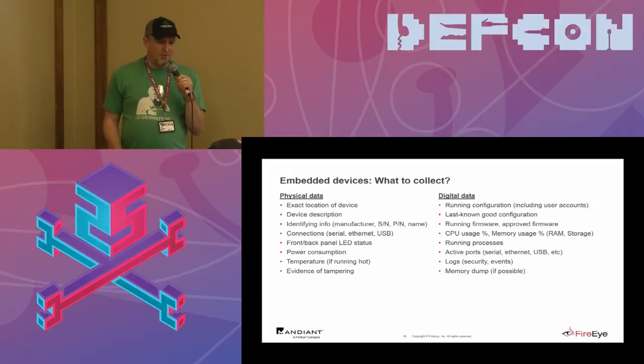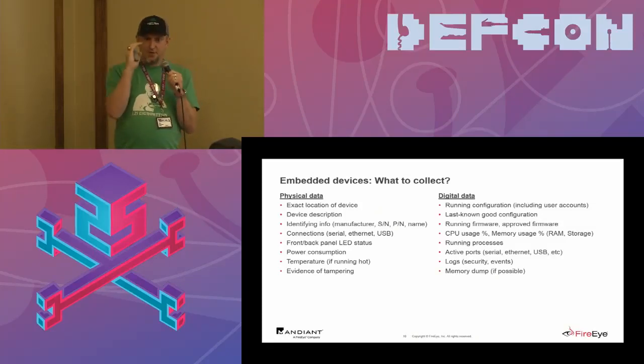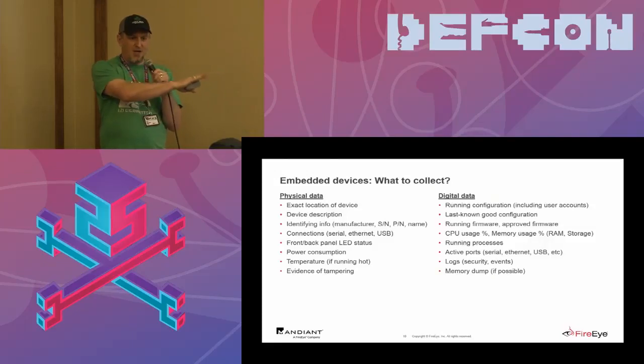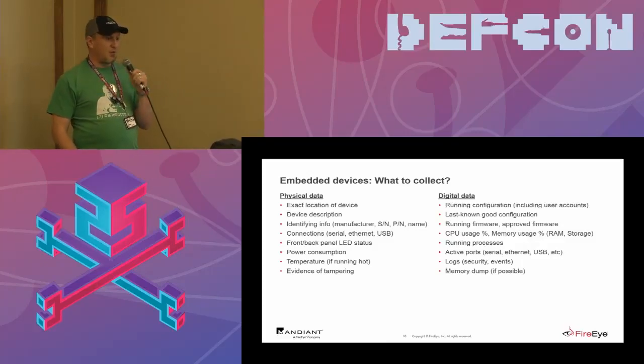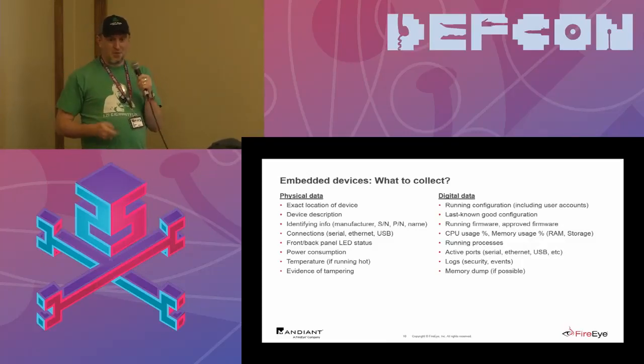Mark Fabro found an HMI that was running hot by using a FLIR camera, and it was hotter than the other HMI. They found out it had a Trojan on it, and it was using more than normal CPU, so it made it run hotter. That's how they detected it with a FLIR camera.